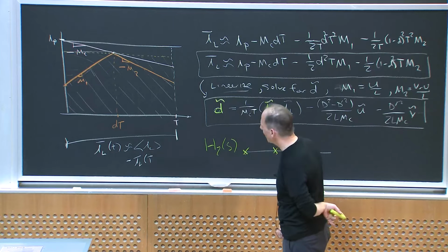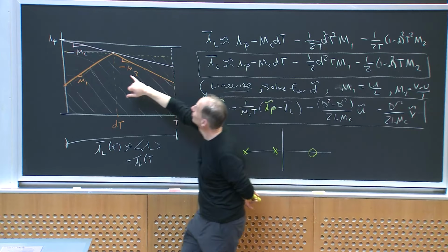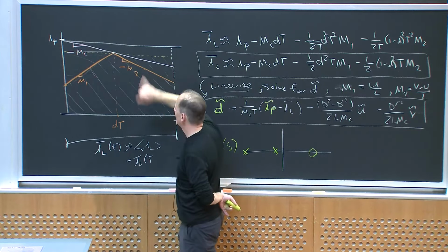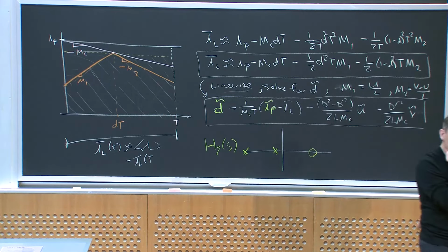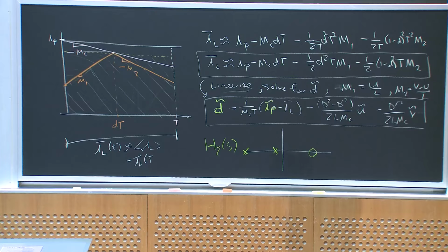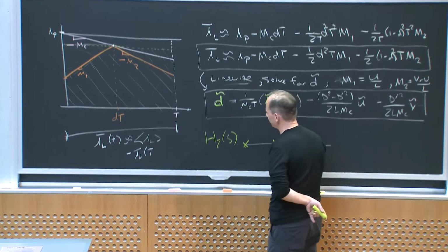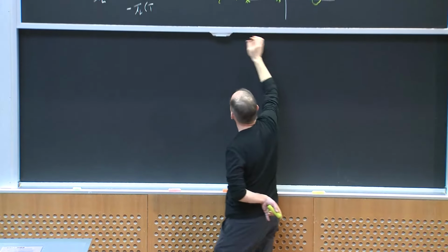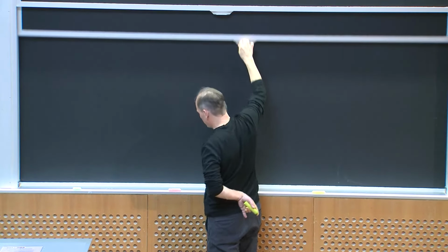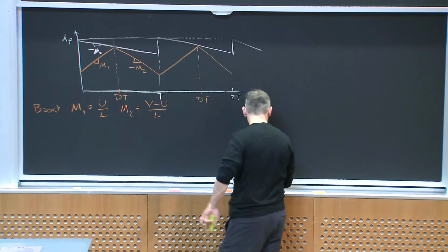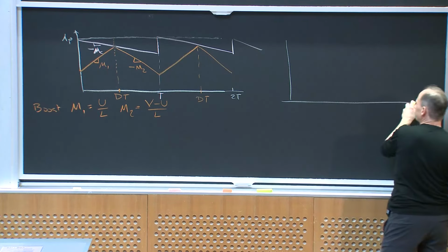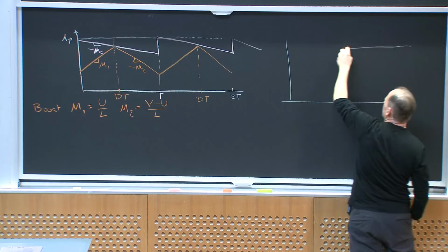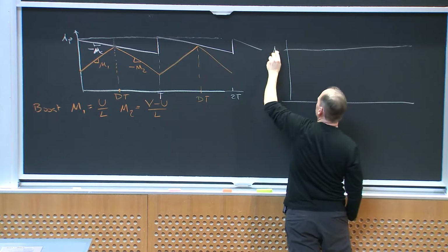Okay. Yeah, why did I even bother with this ramping m_c signal? Like, why not just use I_P? And in some cases you can, but here's the problem with doing that. In some cases, if I do that, this is the situation I can find myself in. I'm going along, and suppose I just have I peak and I get rid of the compensating ramp.